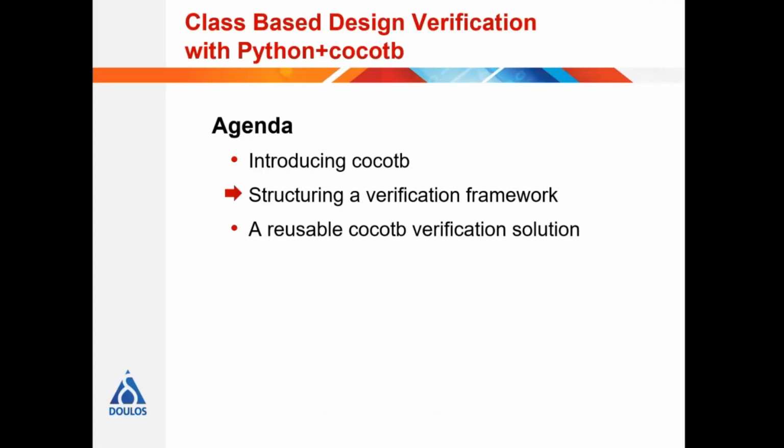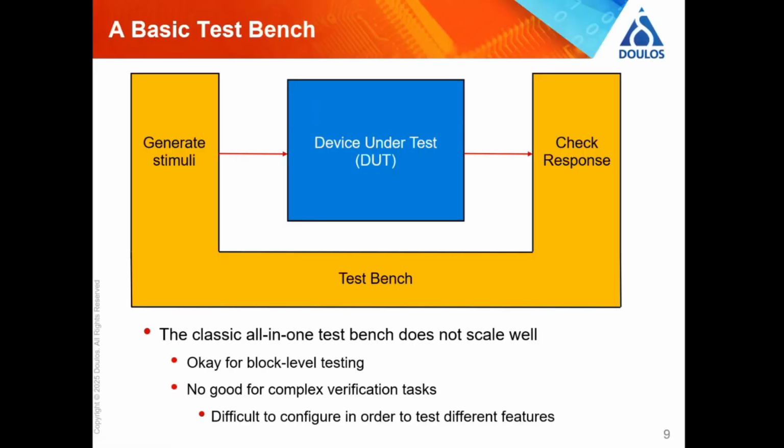So, great, we've got Cocotb. But how do you actually structure your verification framework? Well, this is the old-fashioned way of doing it, and this is perfectly decent if all you're trying to do is simple block-level testing. Nothing wrong with this for a fairly small self-contained block.